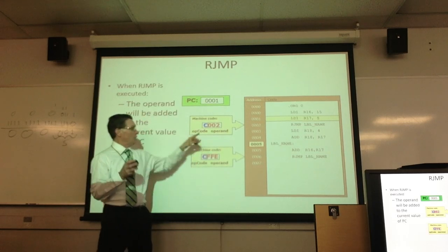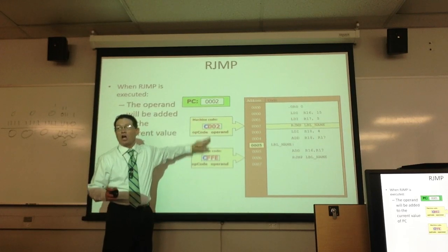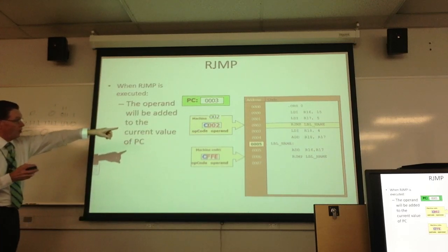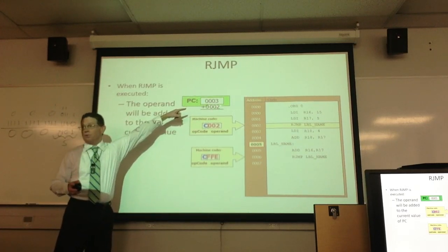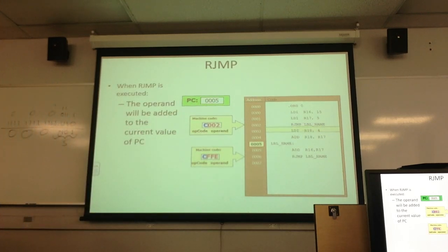All right? So watch what happens when we come down here. You will notice that this is 12 bits, but I need 16 bits. A 0 will pop out of this thing. It just copies it. So notice the 0. Watch another 0 come flying up. That gives me the 16 bits that I add to, because the program counter is 16 bits. I've got 16 bits, and I'm adding 12 bits. It just copies whatever the 12 bits are, 9, 10, 11, 12 get copied, and then just tacked on.